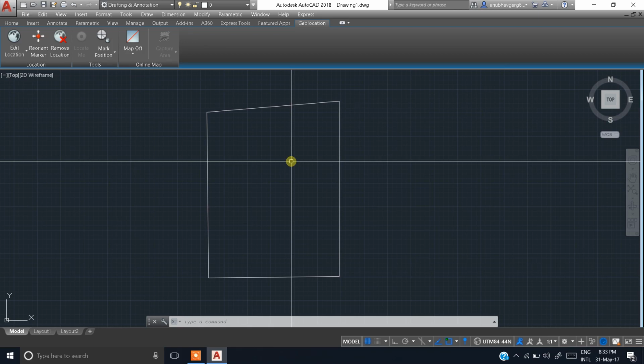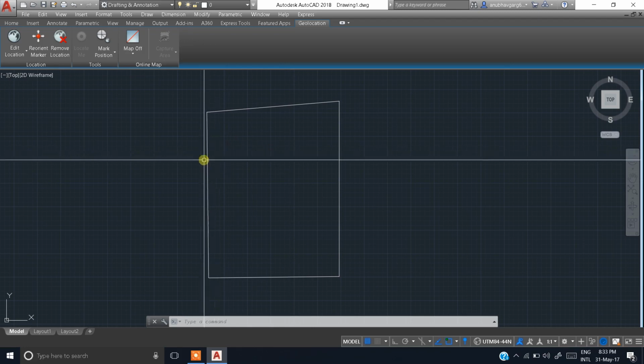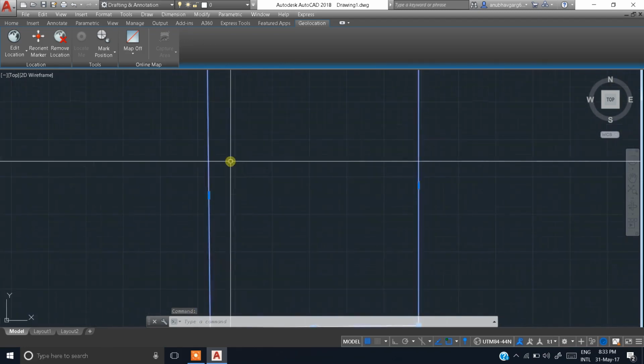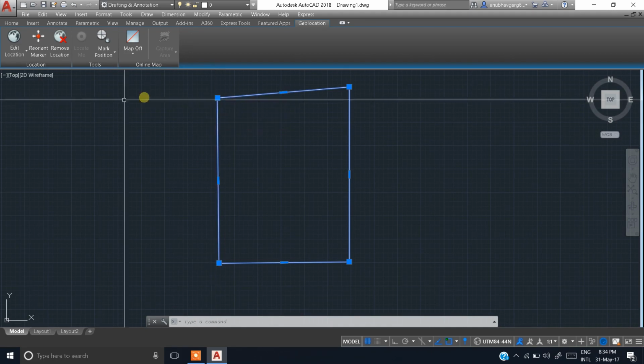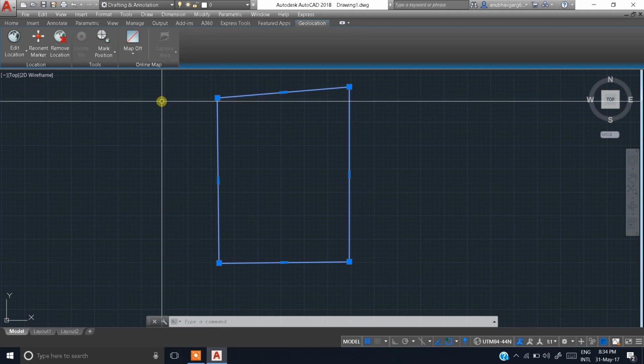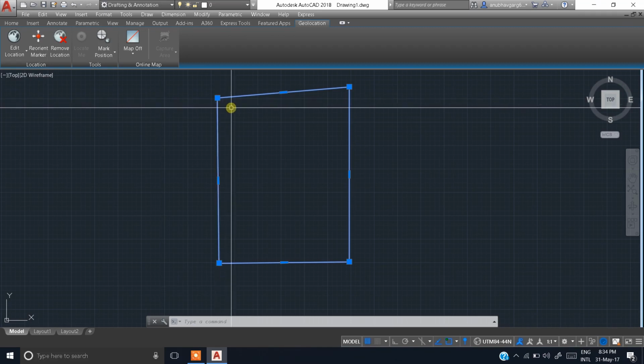Okay, and there's one more technical reason: when you try to utilize each and every corner of the building, then the columns that you provide will be at the edges. And the footing is always a rectangular footing, or maybe a square footing if you're going for the isolated case. You need to provide eccentric footing if you want to create the columns on the outer lines. For instance, this line is my outer line, and if you want to create some columns over here, you'll place columns here, and here, and then here. And the land next to your plot does not belong to you, and you cannot take your footing to that place. So in that case, you need to provide eccentric footing. And believe me guys, I really don't prefer providing eccentric footing. It's better to leave some offset and then start working with it.